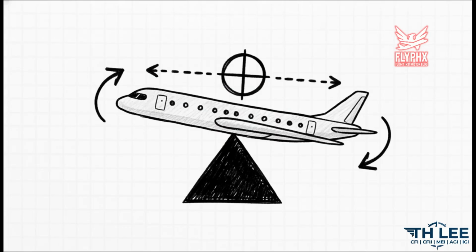And that brings us to one of the most critical safety warnings in all of aviation. Pay close attention here, because miscalculating your center of gravity can absolutely be fatal. The CG is the precise point where the entire mass of the aircraft centers. And here's the kicker. As you burn fuel during your flight, fuel that's situated away from the CG, that center point physically moves, which constantly alters your flight stability.